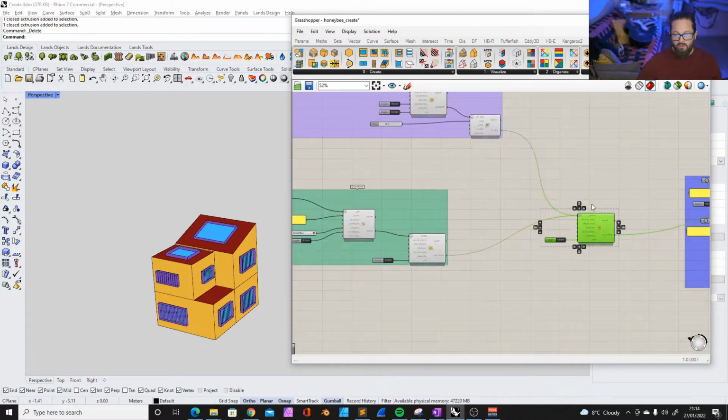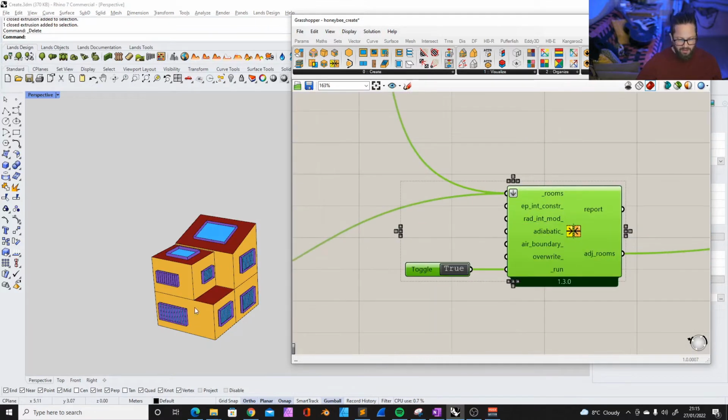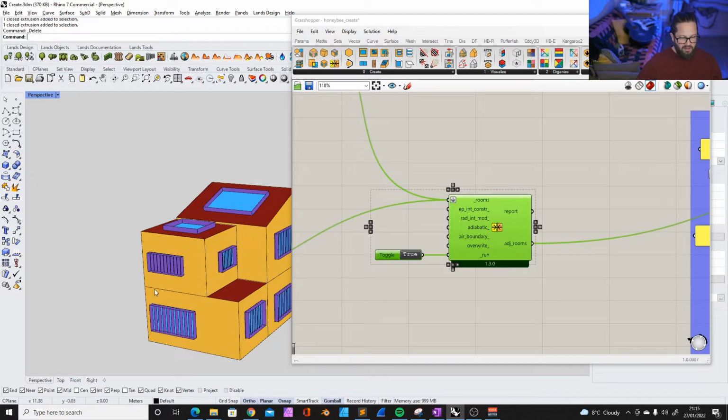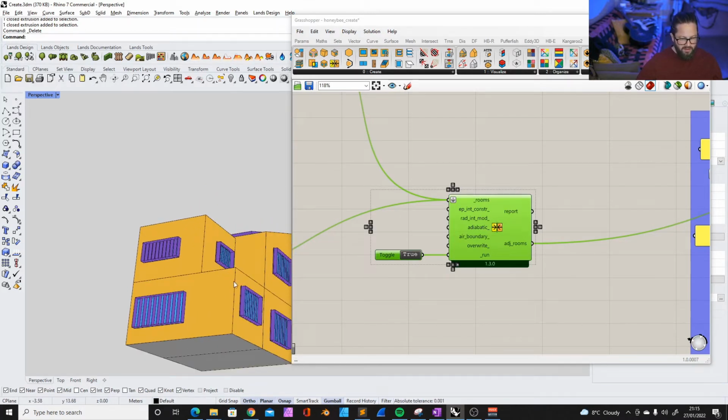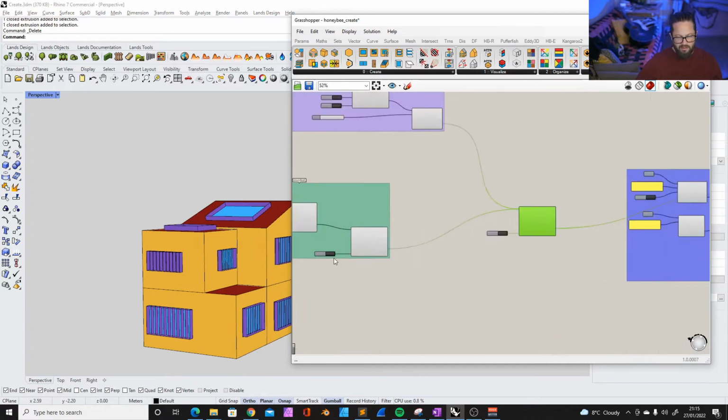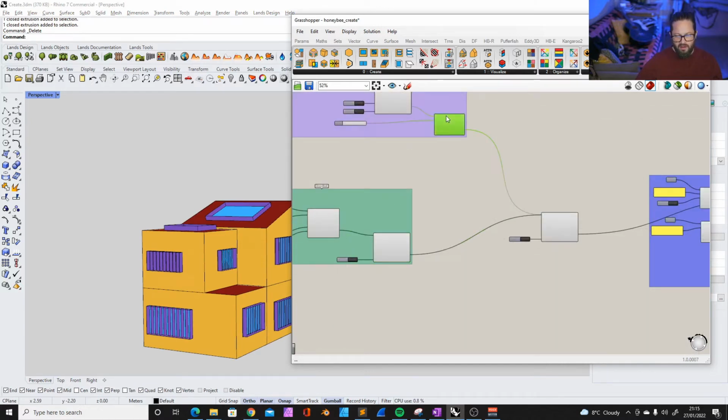And then we need to run the adjacency tool again, so Honeybee knows from both sets how they connect to each other. Now Honeybee knows that the surface below that small box must be a floor, but it's not a ground floor, because it sits on top of the other one, so it can't be a ground floor, but it's a floor. And from the other side, it knows that this surface inside is going to be a ceiling. That's why we need to run it twice. So we ran it once here and then another time.